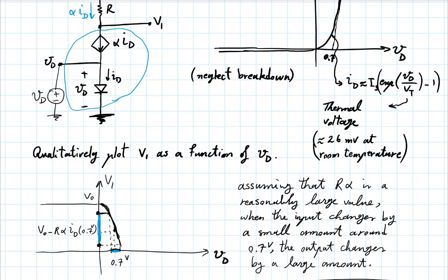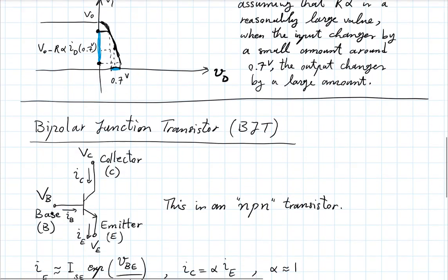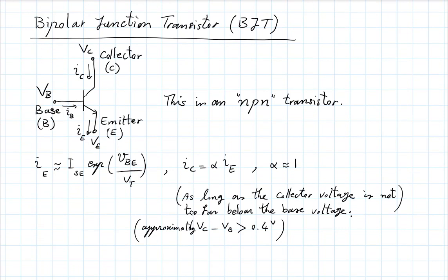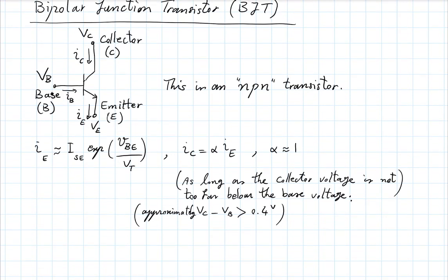The output current is not negative here. Why do you say it's negative? Let's look at these currents. What's happening here? What does KCL say for this device? If you consider the fact that charge is supposed to not be accumulated in here, the sum of currents going in should equal whatever comes out, right?